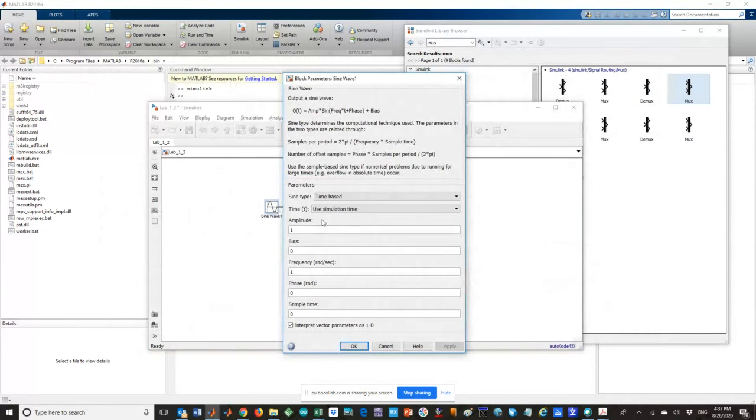And if we need the external one, we can use external signal where we can use this time simulation. Okay, we keep these two parameters as default parameters. Amplitude, I'll make it 120 volts, for example, as a peak value. Bias, we don't need to bias this one.